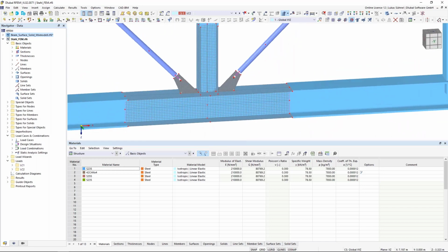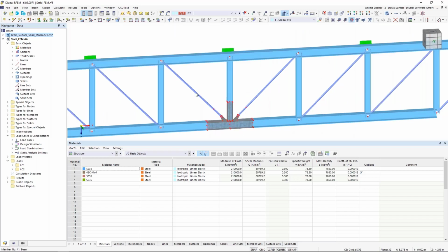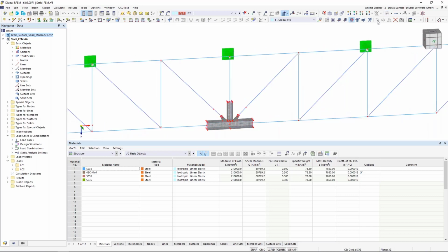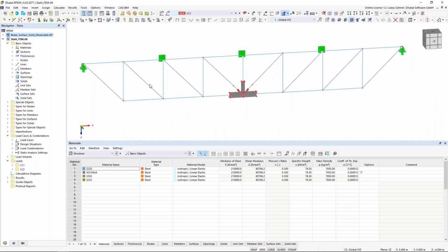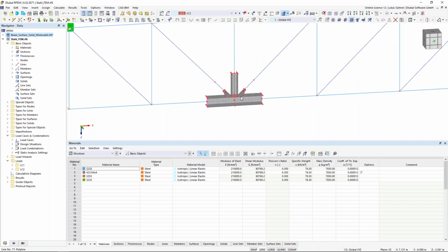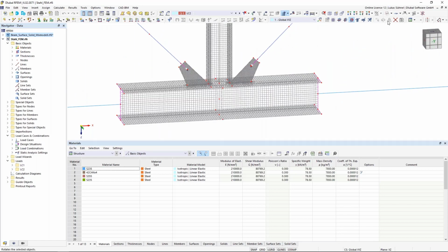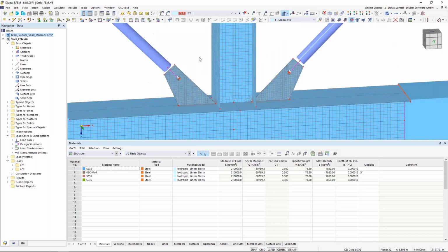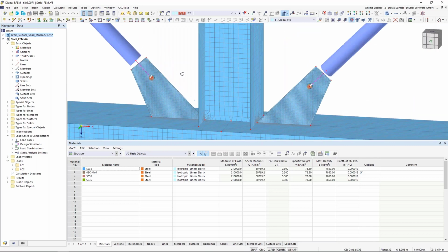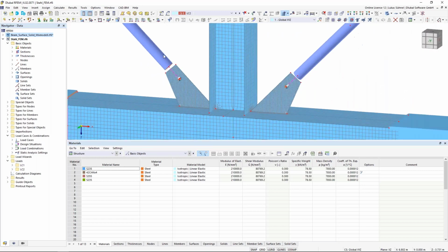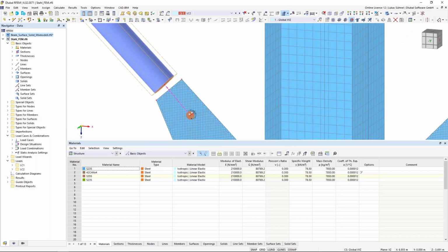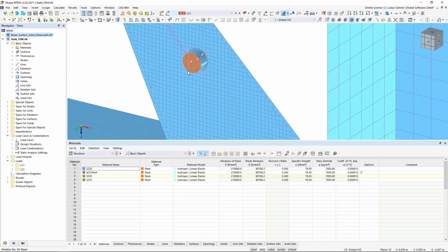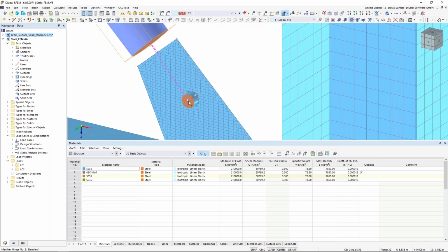And one particular detail joint I wanted to analyze with surfaces, basically. You can see the rest of the structure is again a beam structure, a 1D element structure, and this specific detail I want to analyze in detail using surfaces. I modeled the connection plates here, these tension members are connected to this bolt, and this bolt transfers then the forces onto my connection plate.